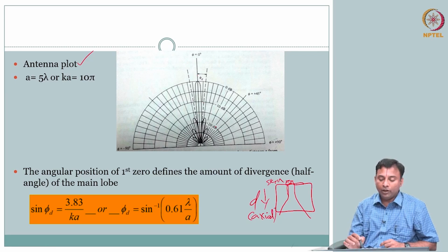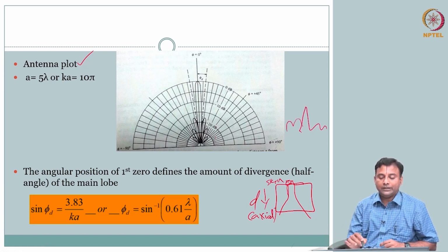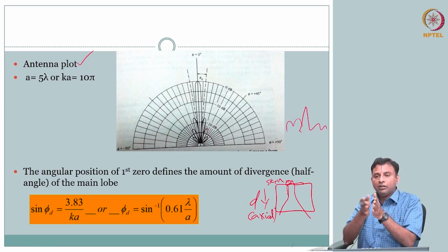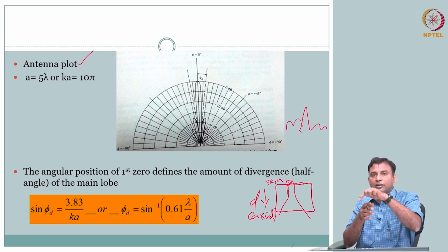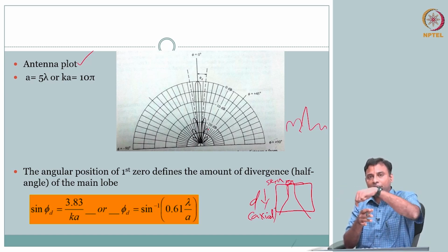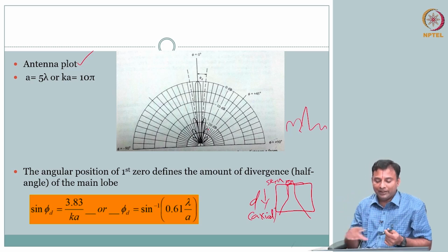So you have your main lobe. Remember how I showed there is a fluctuation in the near field? You had main lobes and side lobes. So you can see all that here. If I am trying to insonify only the front of the transducer, unfortunately because of the size and shape of the transducer, you get different pressure experiences in the field. So there is a pattern to it, so we call it the field pattern.